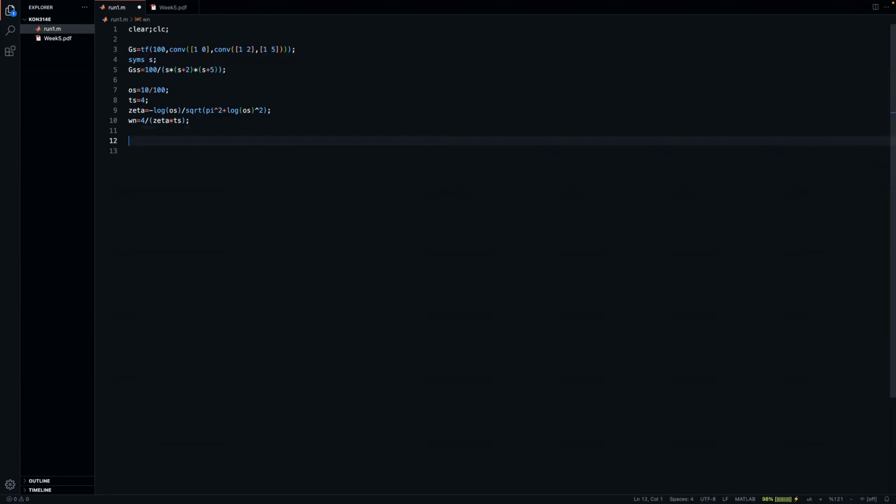That's nice. Other than that, what I also know is I want to design a PID controller. And we have talked about the fact that the PID controller transfer function can look quite different from each other. One of the realizations or constructions of a PID controller could look like this. Another one would be KD times s squared plus KP times s plus KI, the whole thing divided by s. Another one would be, if you do the math here, you will get this exact term here, which is more like it.